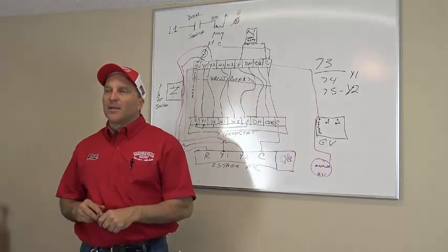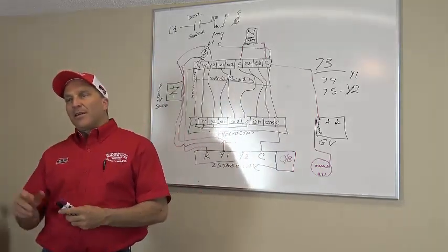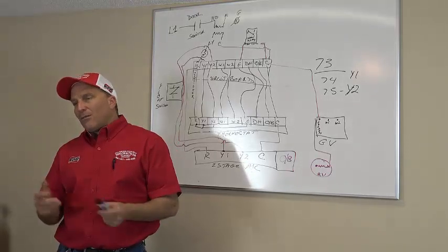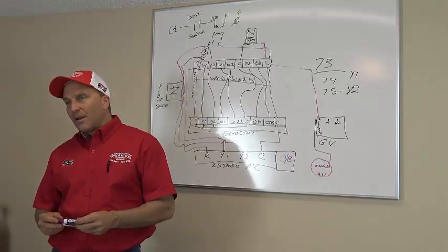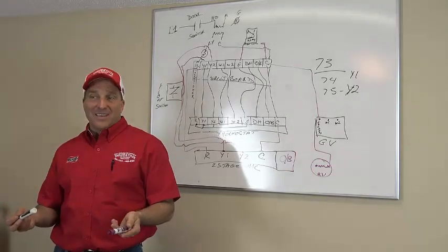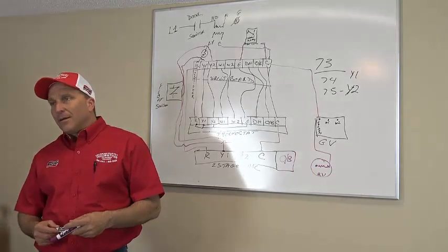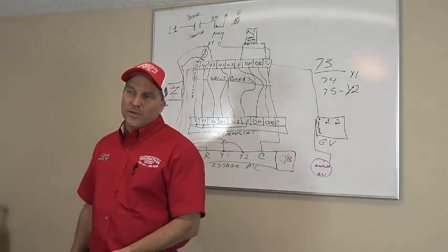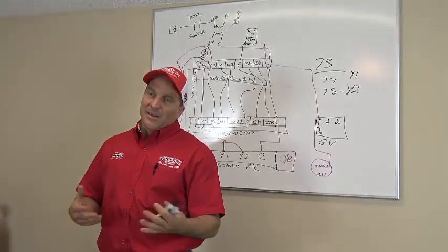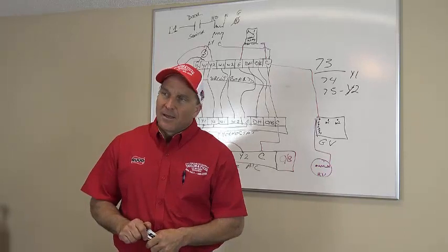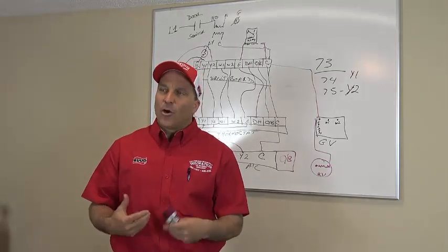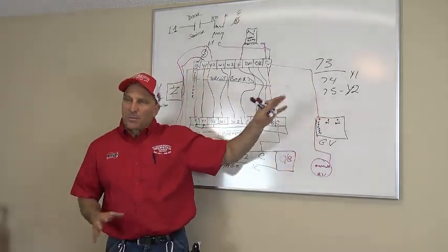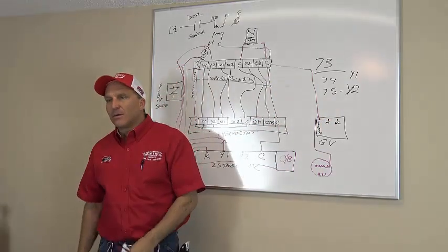Whereas with today's units, I don't even like to tell a customer that I can take their split capacitor motor on that existing furnace and make it a 2-stage system. Why? Because you're not getting proper performance out of that system. Will I make it work? Yeah. Have I done it before for that customer? Yes, I have. Let's say that furnace is only 2 years old. Am I going to sell them a brand new furnace when it's 2 years old? No, I'm not. And let's say they want that 16-SEER 2-stage system. I'm just going to make it work the way I know how. It's still going to give them 2 stages and still lower the blower speed. It's just not going to be perfect like the variable speed will make it perfect, but it'll be damn close.